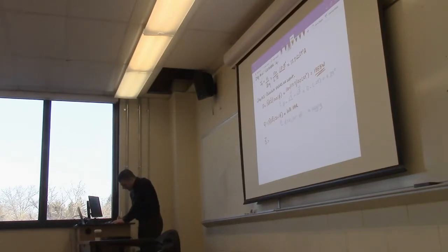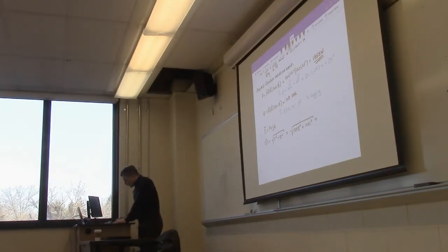So I don't think I even need to write out the numbers. I'm just going to say it's equal to P plus jQ. We know that. And then lastly, it asks us for the magnitude of our apparent power. That's going to be the square root of P squared plus Q squared, which equals the magnitude of 1858 squared plus 1031 squared, which equals 2125 volt amps.